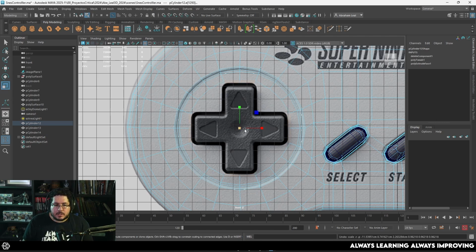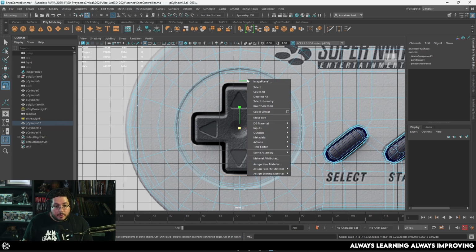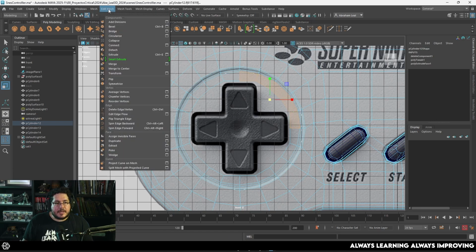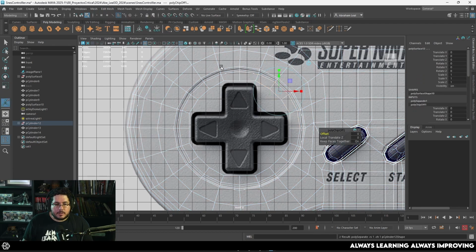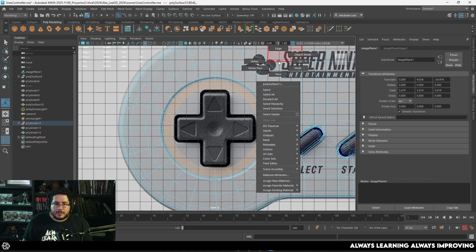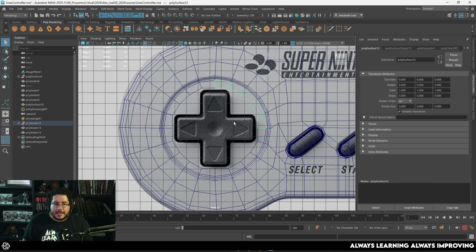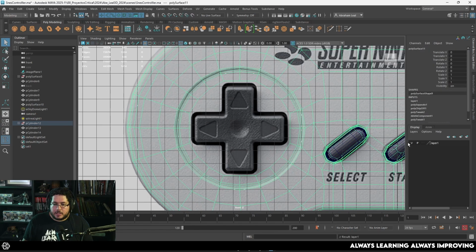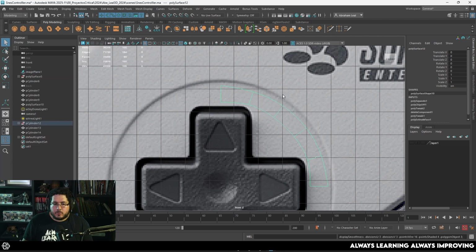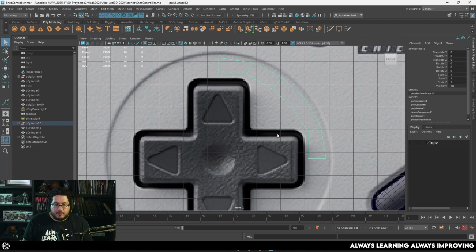And one of the things, actually, let's go back here. One of the things that I've always mentioned to you guys is you need to learn how to work smart, not hard. So here's what I'm going to do. I'm going to grab just a quarter of these faces right here. Okay, just a quarter. I'm going to say edit mesh and duplicate. So now I got this object and that object right there. This one, I'm going to get into a layer and hide it for just a second so that I can focus on this one. Because I know that when I press number 3, the border on this one's going to be really clean. And we can very easily merge this or stitch it back together with the other one.